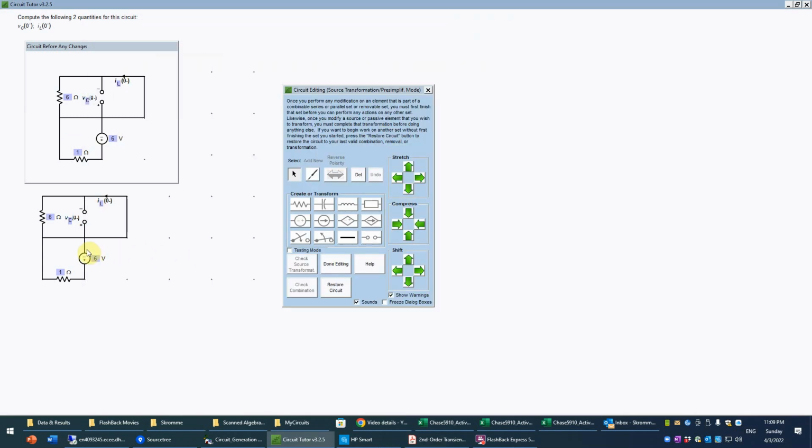A key feature here that will really help you notice, instead of doing a full-blown mesh analysis or something like that, is that there's a wire going all the way across the circuit, cutting it basically in half. As you may remember, that means the circuit is in fact hinged. In other words, if I remove this node here and all its associated things, that's basically going to split the circuit in two. And so what happens over here is not going to affect what happens over here. You really can't feel it at all.